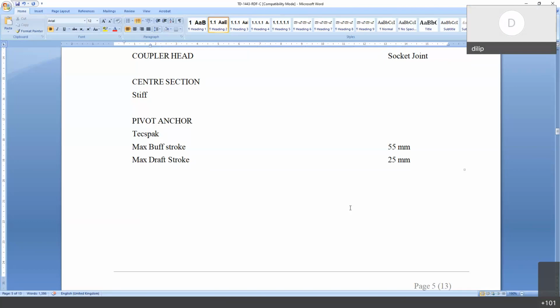Because the complete train is coupled and all the doors are automatic doors, but in case of fire the cables get damaged, so the cables of the automatic doors, they are fire survival cables. Even in case of fire also these cables will not get damaged. So all the doors can open and the passengers can travel to both ends. Evacuation can be faster, because the driver cab is also connected. The driver cab is connected to the complete train. So driver cab doors can also be opened, and the complete train is basically connected.